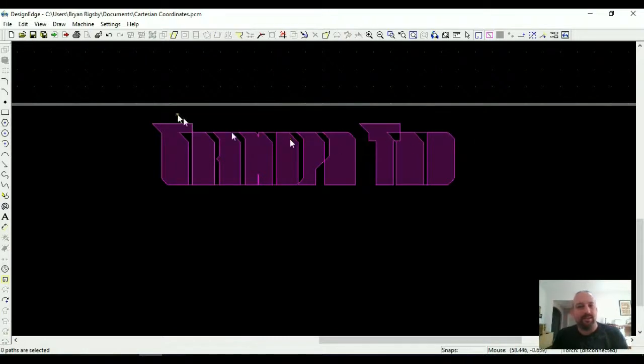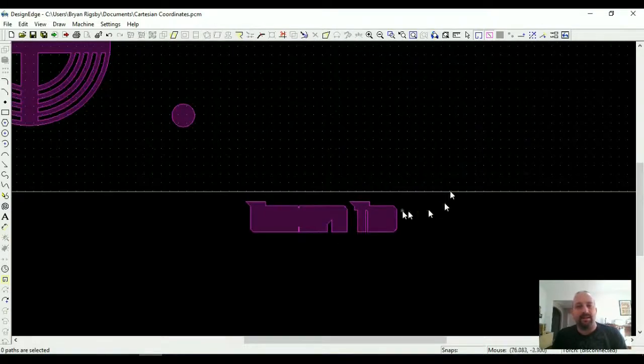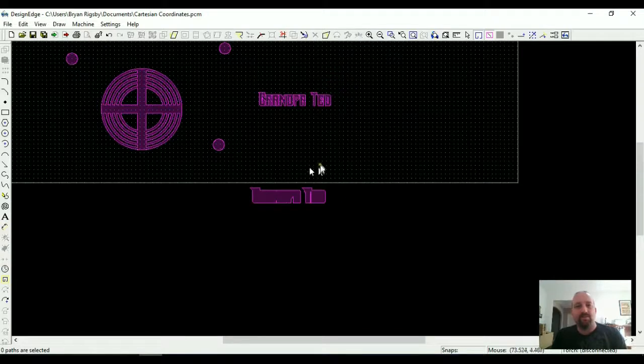I have that other places. And then I can Control B to combine all of that. And now I have this nice full piece around it. So watch what happens when I want to put that box back around it. I can grab it all. I'm going to hold Control and unselect my reference circle because I don't need to copy it every time or move it around.